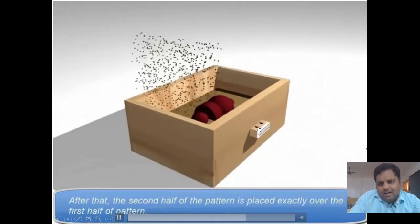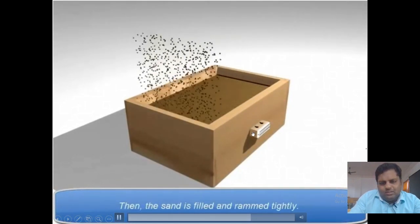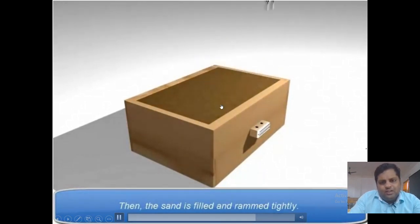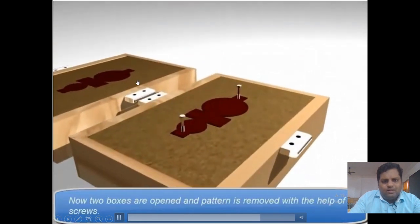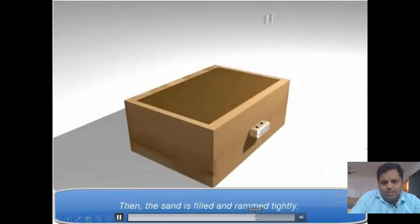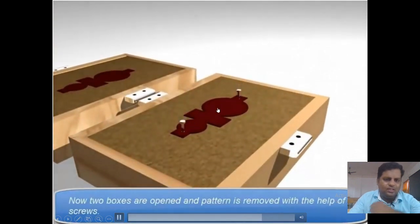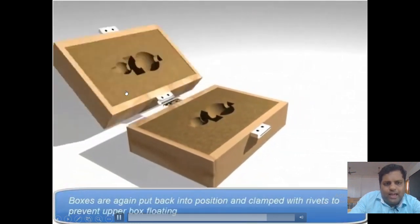This is the lock for the cope and drag, so that they do not move during the ramming process. Now the sand is poured on it, and now the cope and drag have been removed. We remove the pattern from the sand using lift pins. The pin you can see here is the lift pin. We are removing the pattern, so that we get the mold cavity.